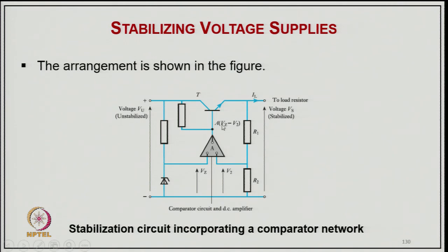Again we have a transistor amplifier, and we have an output voltage here. So, we are taking as a reference a voltage generated from the output voltage, which is well regulated, and we consider this a proportional-type voltage stabilizer, because we consider the output voltage to be well regulated. So, we are taking part of this as a reference voltage, and the feedback voltage we are taking from the input, with the typical kind of biasing, which is unstabilized voltage to this amplifier, from which we derive the base current.